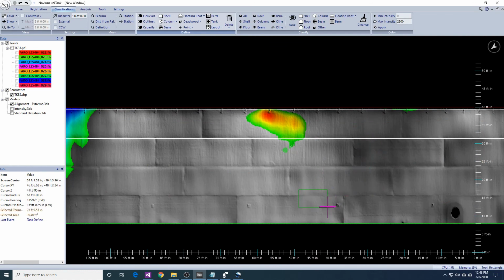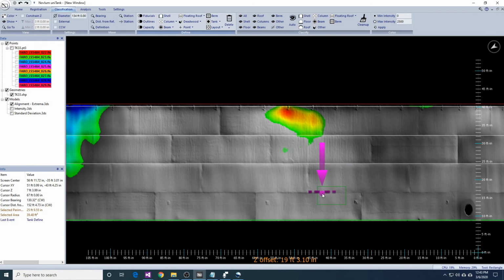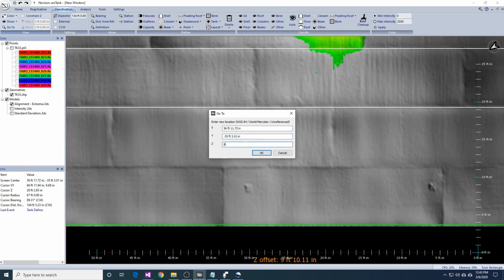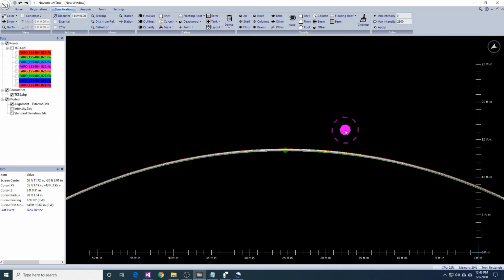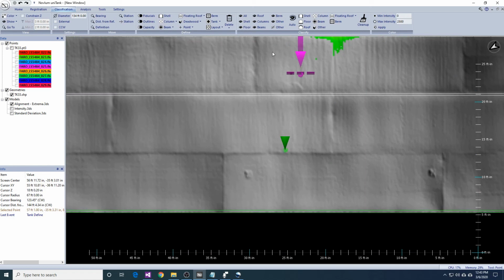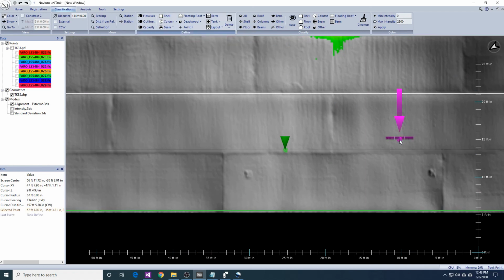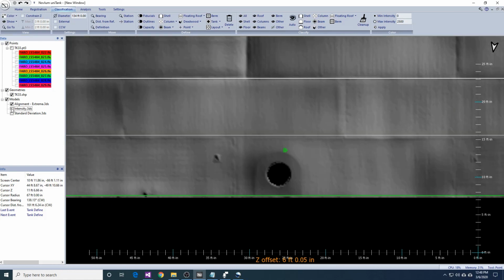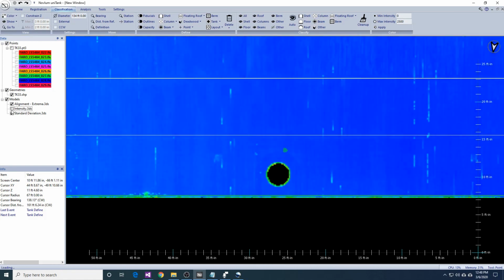If you need to set a course at an exact elevation, you can do this by setting your elevation using the Go To feature. Looking from top view, drop a course point at this elevation. Once this is completed, I can go and identify the shell plates. Again, I can do this in two ways.